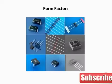There are many kinds of diodes available with many package variations. In this picture, we see some surface mount diodes, some through-hole diodes, some glass-encased signal diodes, and we also have several packages that have 4 diodes installed in a bridge configuration to give us convenient packages for bridge rectifiers.